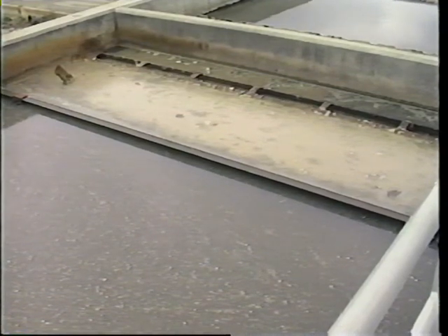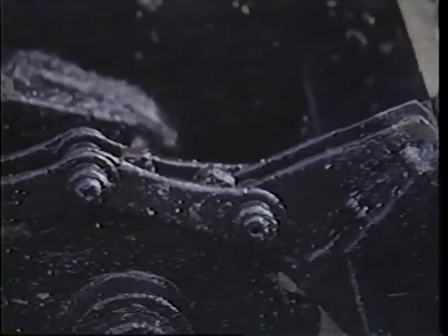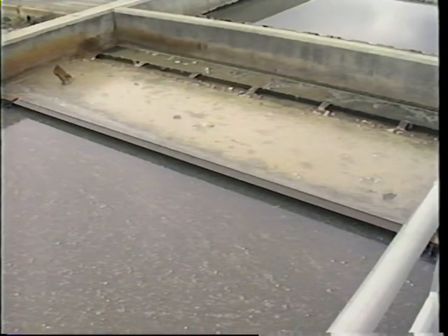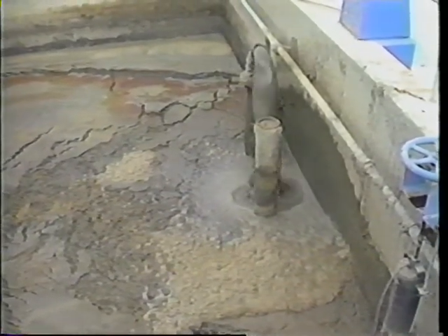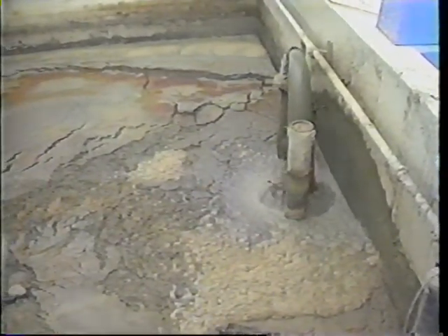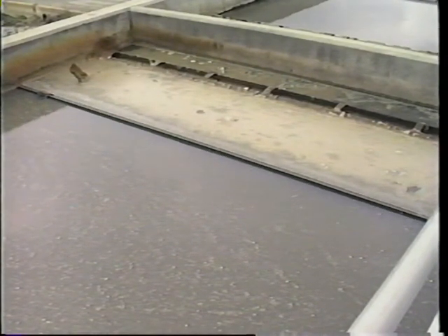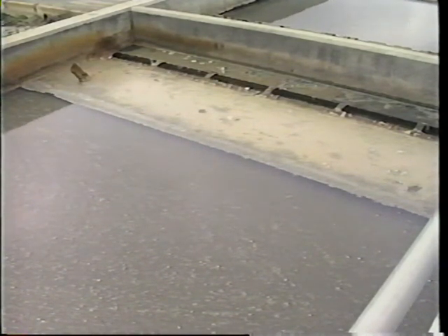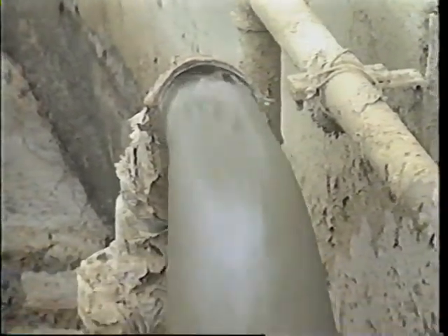Rectangular clarifiers have wooden or fiberglass skimmers, known as flights, which are moved by a continuous loop chain-driven system. The flights skim the surface and push concentrations of scum into a scum removal system that generally diverts the scum to the solids handling portion of the treatment facility. The flights continue their travel to the bottom and scrape the settled biosolids concentration into a hopper, where it is then removed and placed into solids handling facilities. Refer to the illustrations in Chapter 3 of your study manual for a complete view of clarifier design.